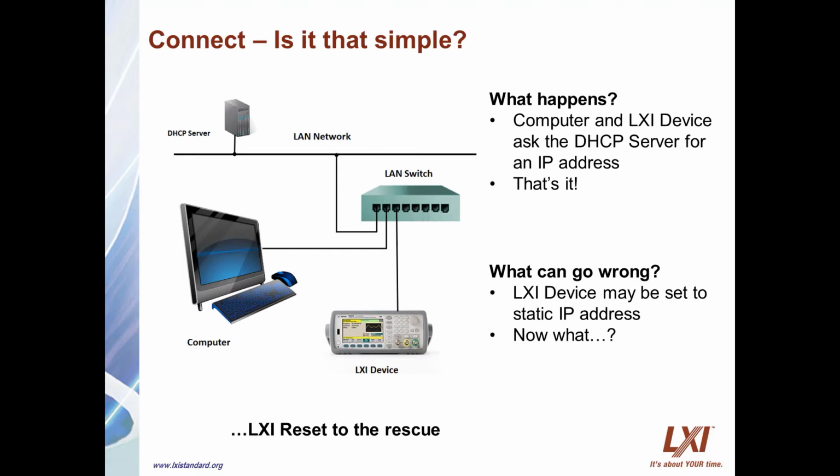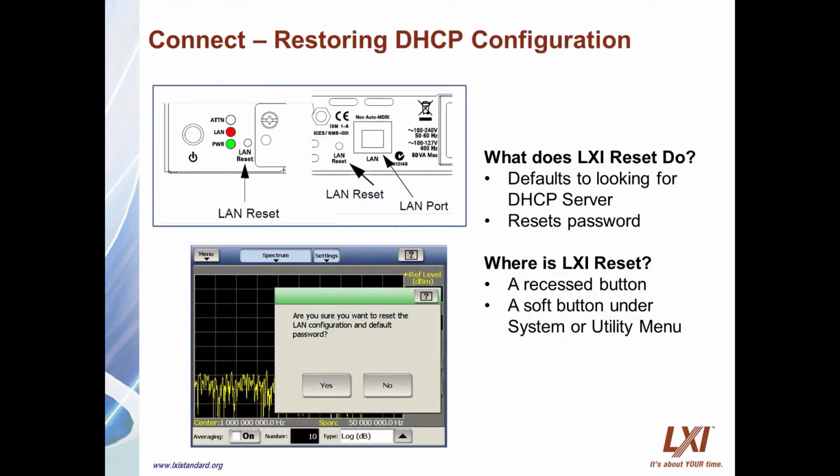And if it doesn't get one, well, what went wrong? Sometimes you might get an LXI device that you've borrowed from someone, and it might have a static IP address. So that's going to cause you a problem. But LXI Reset is going to come to your rescue.